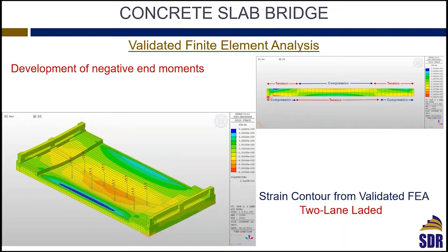you will see what we assume is a simply supported beam with a positive moment. In fact, this strip we're looking at develops negative moment, then you will have positive moment in the middle, so it's closer to a fixed condition. I wouldn't say it's fully fixed, but there is partial fixation, and this partial fixation comes from the boundary condition, which is representing the actual seating of the slab.